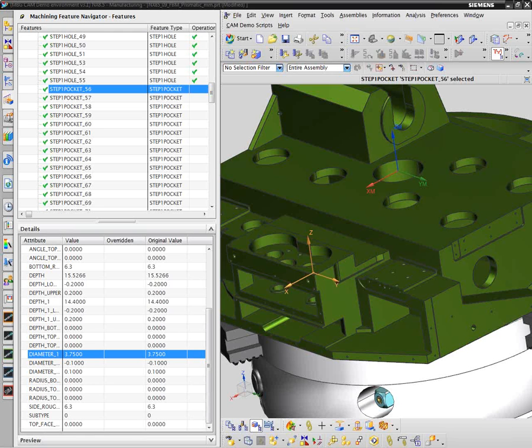You'd have to step through making the decision what tool you want to use, get a blueprint or something out, define all this information, manually go through all of this for the various different hole sizes and stuff. But now, based on the machining knowledge rules, NX can create the operations for all the features, different sizes, all at once, making the tool selections completely automatic, making the process of program generation very easy for these type of features.